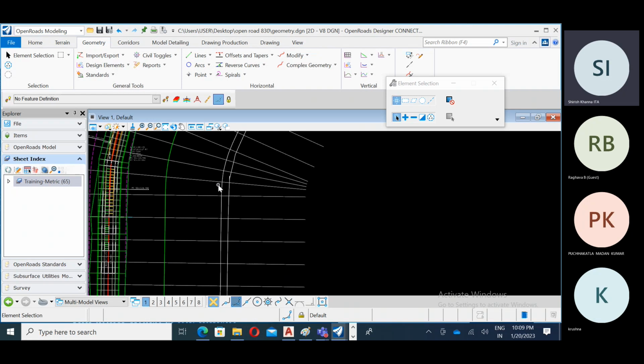You can create it. See, for that portion, you have that kind of data also, no? The hilly area data you need to get first. If you have that, then you have the center line curve. So you need to create that curve with how much radius you require on the curves. First you need to create the master center line, for that you need to use these commands.